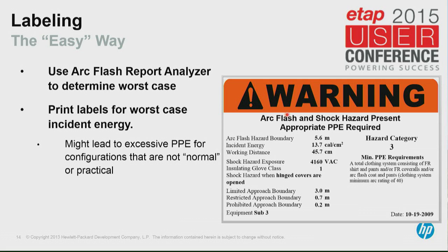What you're really supposed to do is put yourself in an electrically safe working environment, but more importantly, you have to have a work order. If you're doing work on an energized substation or an energized electrical system, you're supposed to create a work order, a method of procedure, MOP, to do it. So our position has changed. What we have decided to do,